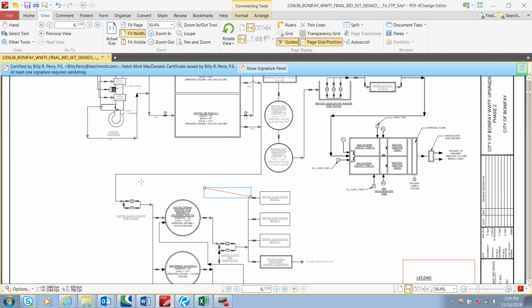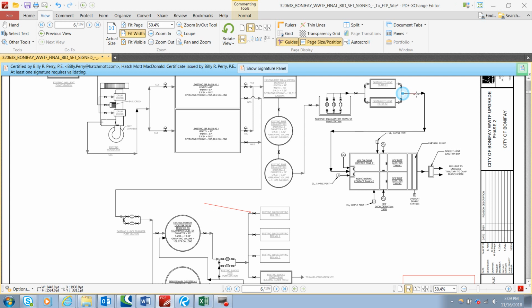Another thing that this flow diagram does is have corresponding lines and arrows that indicate the path of flow. If it's two-way flow, then you would have an arrow pointed each way, but by, for instance, this line here, which is here, here, and here, all the arrows are pointed one way, so that means that there's only possibility of flow one way. Again, you could have flow two ways, but in this case it's not.